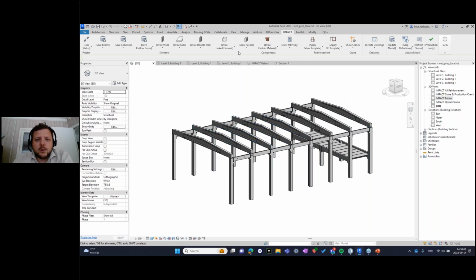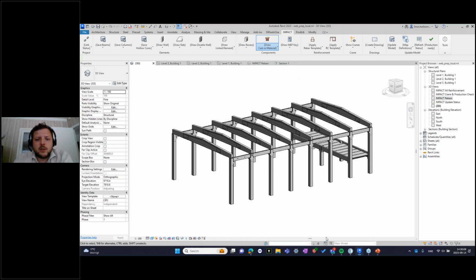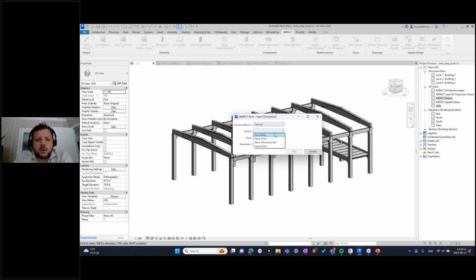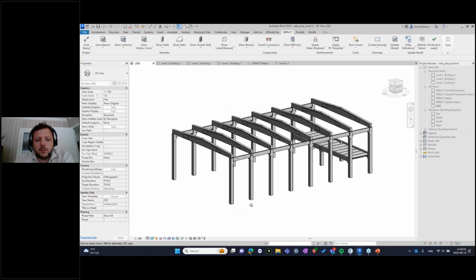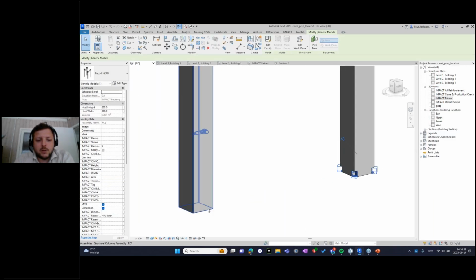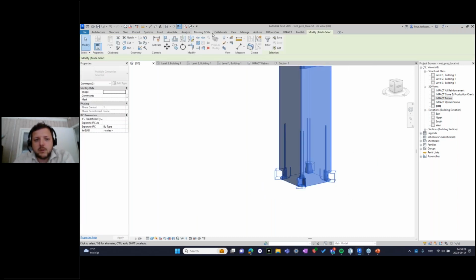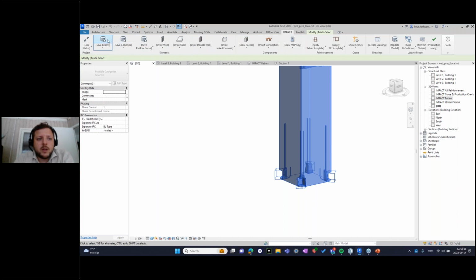Yes, so the thing that I want to show you is these connections. So here I could select the connections for the bottom of the corbels or for the columns, and place custom materials accordingly. I'll just do it for one now because I saved everything else, but let's save this one.